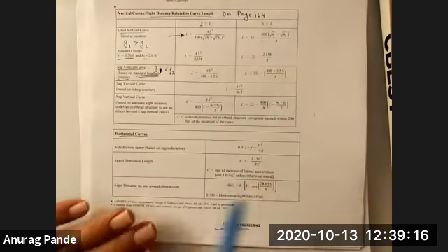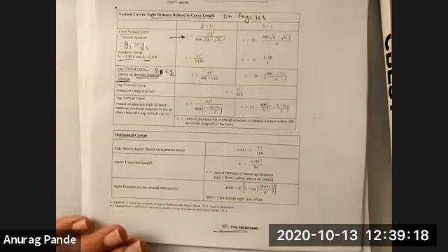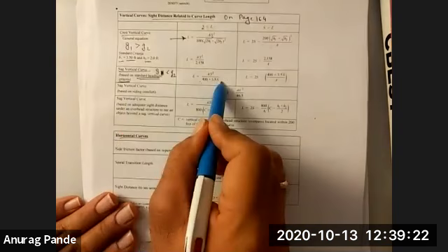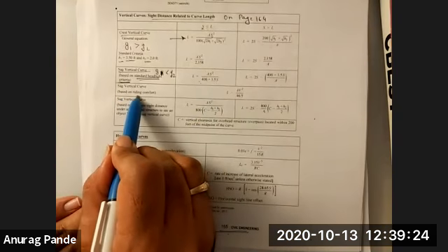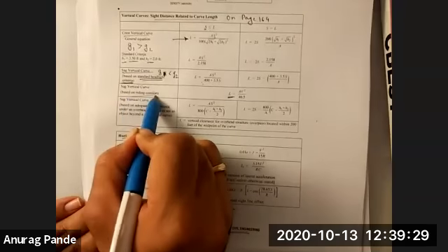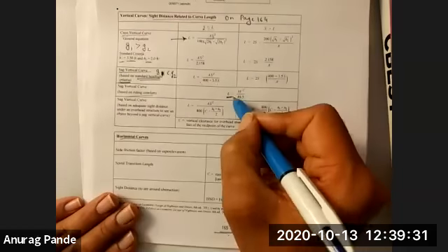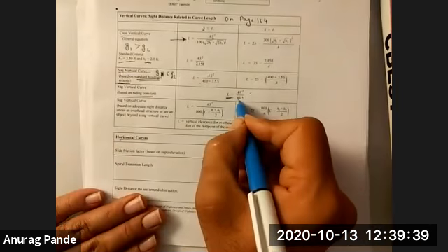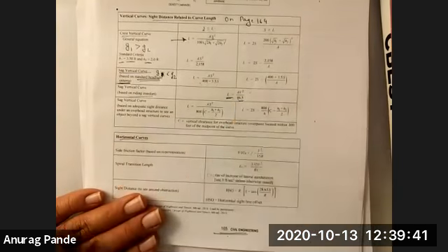Now, there might be other considerations on the sag vertical curve. This is the standard headlight criteria, but you also have to make sure that the minimum length is provided based on riding comfort. So there is another criteria based on riding comfort. You want to make sure that the dip is not very, very steep in nature, so you calculate the L value based off of that.